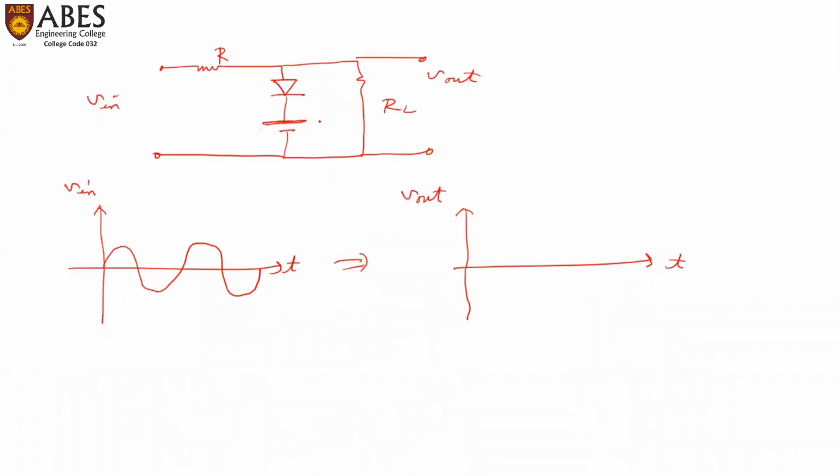So if I have taken this battery potential as 2 volt and input as plus minus 5 volt, then I can say that output voltage will follow the input voltage for the negative half cycle completely, while for positive half cycle it will follow up to 2 volt only, and then it will be stuck at this value like this, and the upper portion we will not get.